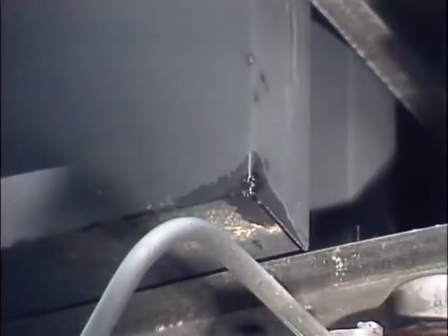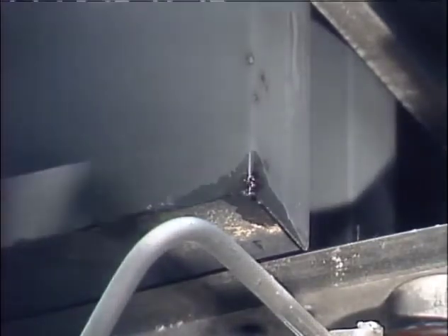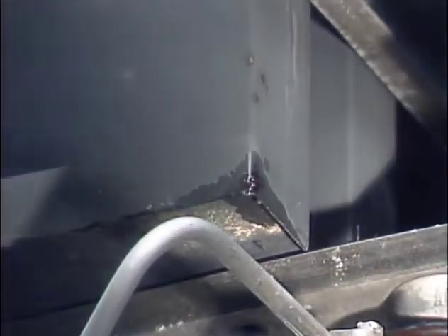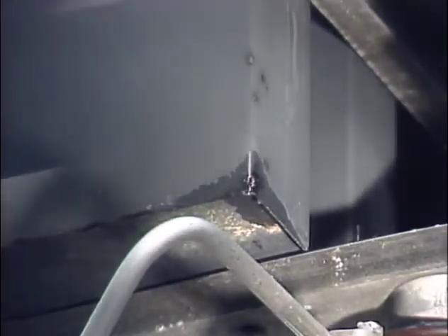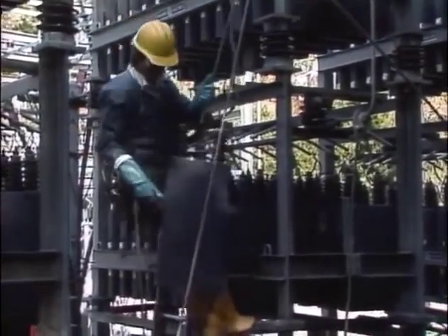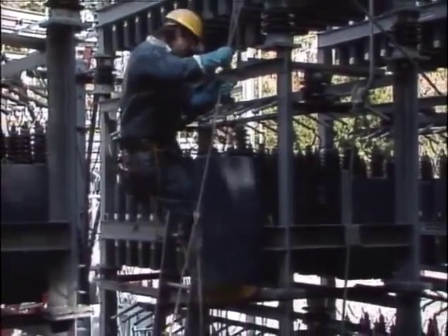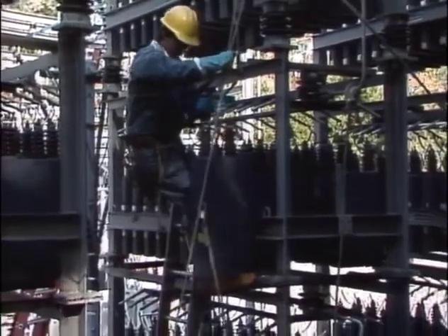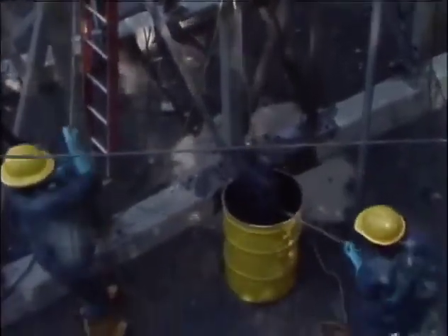Finally, special precautions should be taken when working with a damaged capacitor that contains PCBs. If a capacitor is not labeled, assume that it contains PCBs and observe the appropriate precautions. Generally, appropriate precautions include wearing approved protective equipment, such as a protective suit, boots, gloves, and eye protection. When the damaged PCB capacitor is removed, it is placed in an approved container until it can be properly disposed of.